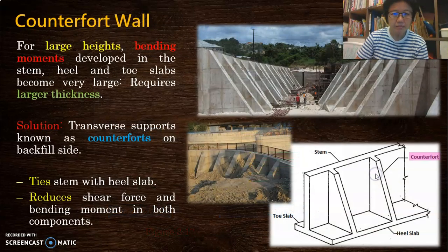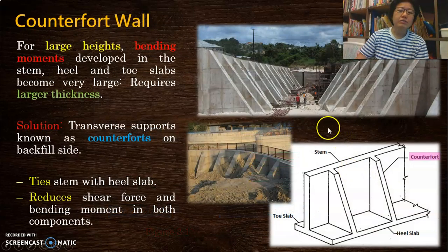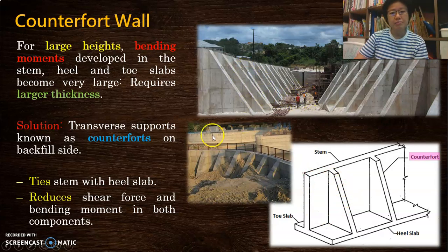Alright? Okay, these are the counterforts. As you can see, it's essentially a cantilever wall, but it has a counterfort at the back, and this is how they look like, how huge and how tall they are. These are the workers, right? They are being backfilled with the soil eventually as a retaining structure. Okay, the vertical bit is the stem and the base is a slab.